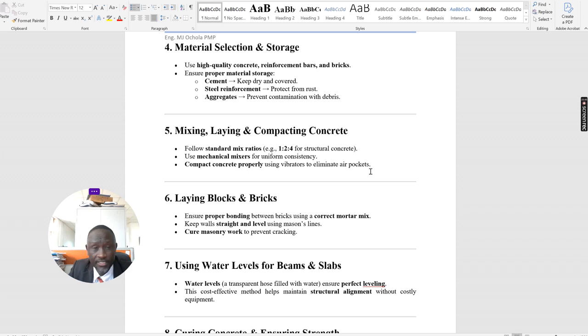I've told you if you are dealing with twin construction where you are building the block walls first, and later on you cast your concrete, that means almost 80% of your block walling is actually load carrying wall. It is a load bearing wall, so you have to be a bit mindful. That means the mortar you use and the brick strength are all indicated and all in reference to the load effect. Yep, so that is important.